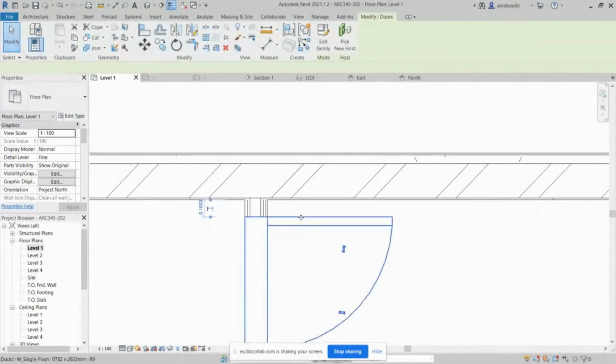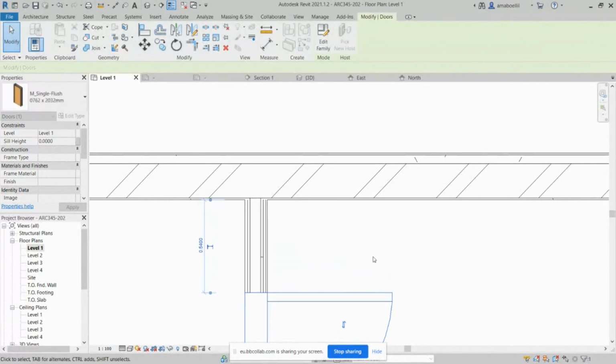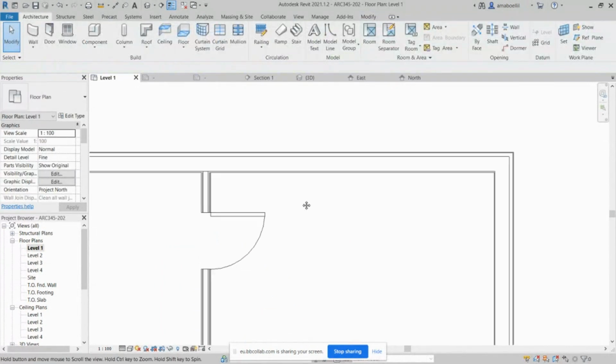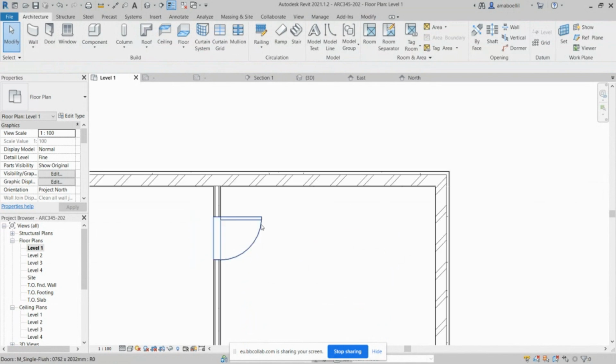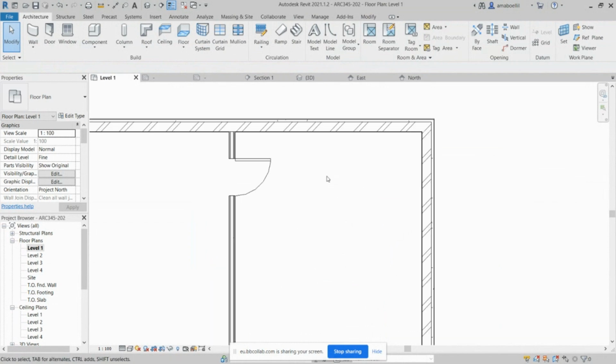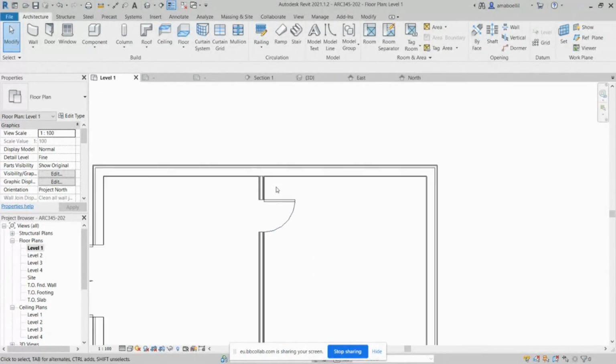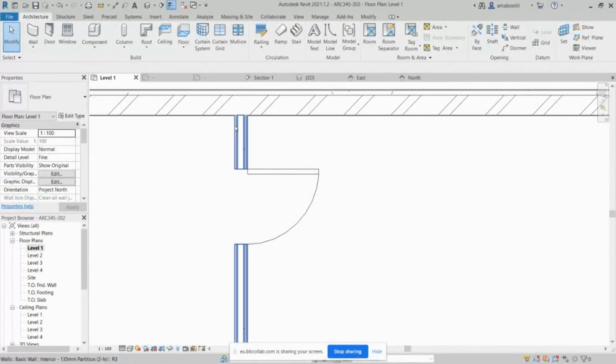Or the other option is to make this at least 60 centimeters, and that is for a purpose. If it's a residential or an office building or something like this, you can accommodate a piece of furniture behind here, a wardrobe, or you can make a cabinet, something like this, and that should be at least 60 centimeters. Most of the time the door is closed, and you make use of the space behind it. Even in bathrooms, you can accommodate a shower or something behind that door. If you make it close to the wall here, this space is completely wasted. Whereas if you make it 60, 70 centimeters and then place something behind it, you can still use it. This is just architecturally, but structure-wise, we need to make sure that we are away by at least one brick length.